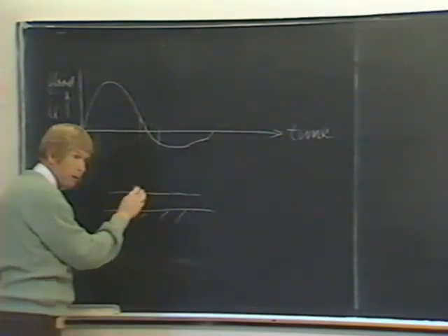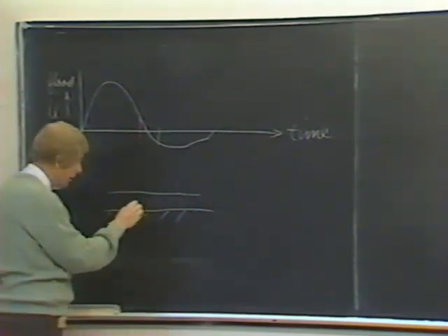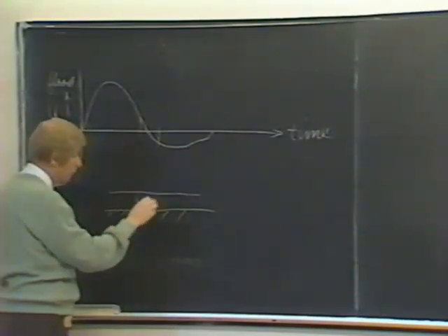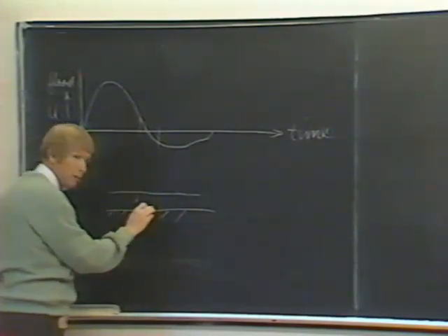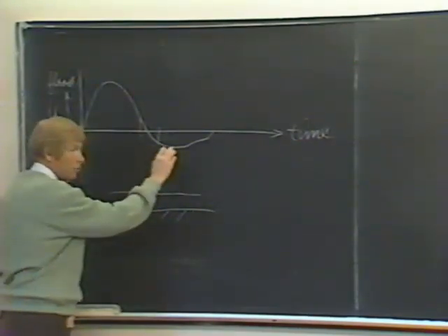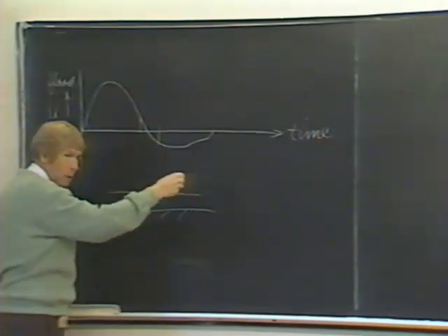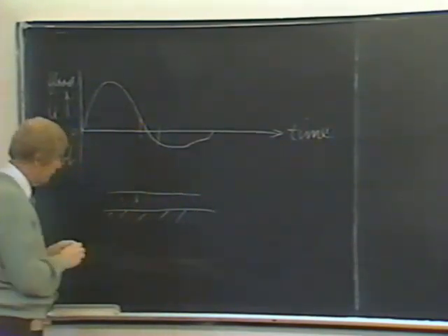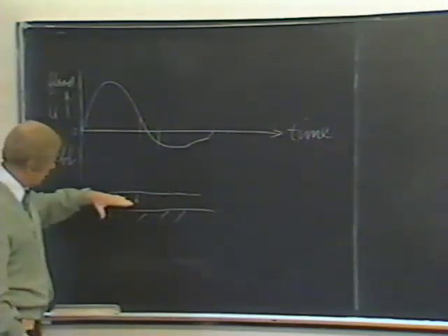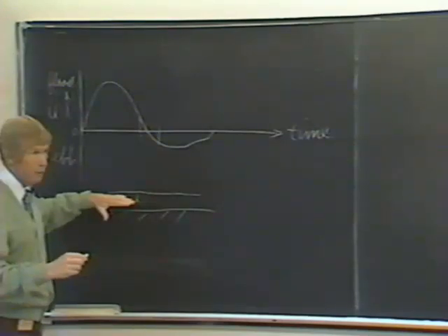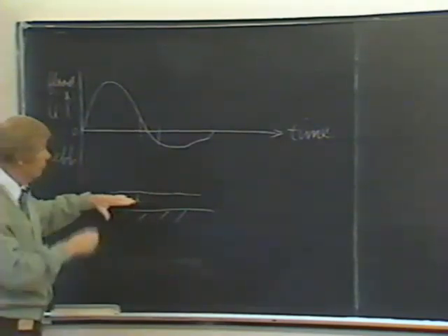So there's a net flow upstream. See, this is current here. So the area under this is the distance that it moves, right? In this case, upstream. In this case, downstream. So the distance that moved upstream here is greater than the distance downstream on this illustration. And that's typical of near bed velocities. I'll bring some actual examples and give you a slideshow.